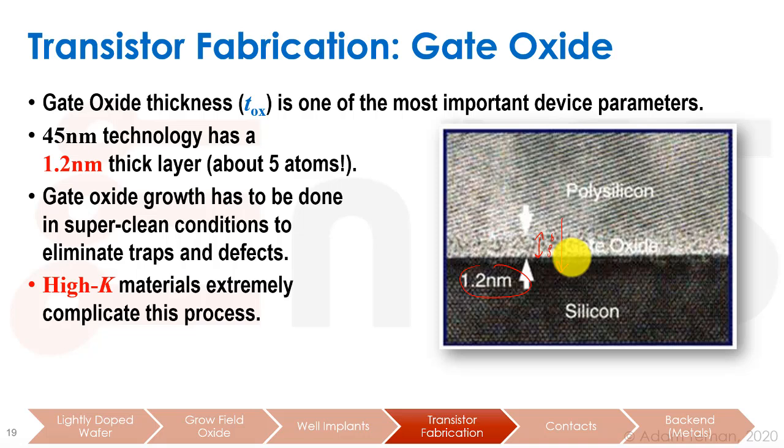Just an interesting anecdote here. One of the reasons that silicon is the material of choice, the substrate that we use, is because we were able to build MOSFETs by oxidizing silicon and getting silicon dioxide. This is a very nice chemical reaction where we get a good interface, where the gate oxide connects really well to the silicon substrate, and we can grow it very clean. So that's one of the reasons silicon won out.